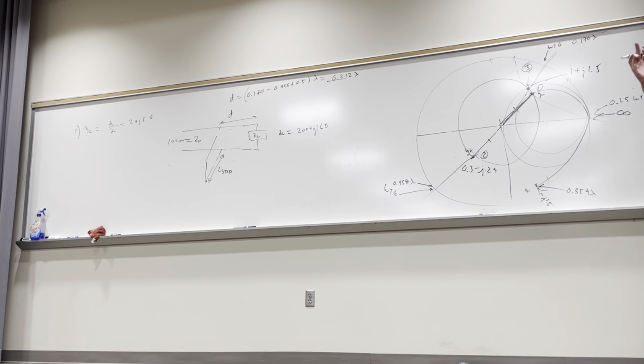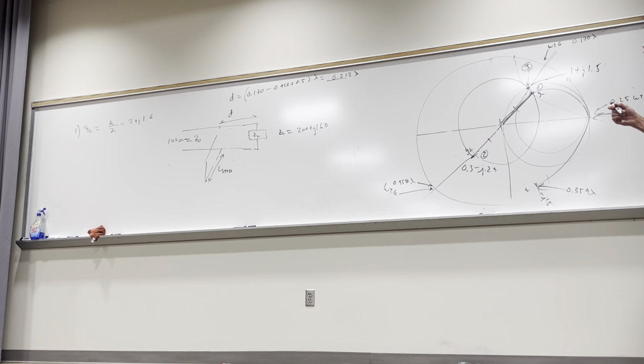We're right on the hairy edge of where it starts not looking like a transmission line, because the signal doesn't have time to start developing the magnetic and electric field energies in there to cause it to look like a true transmission line. But it's close, and you can get away with it for this one.